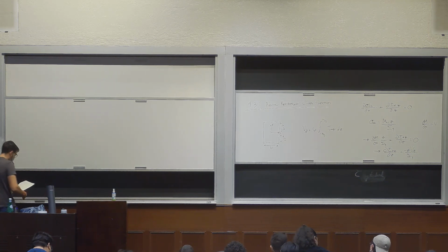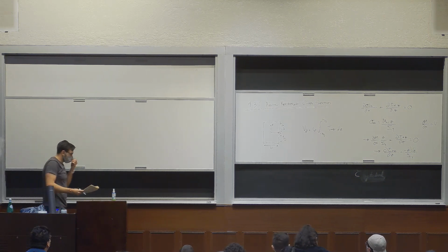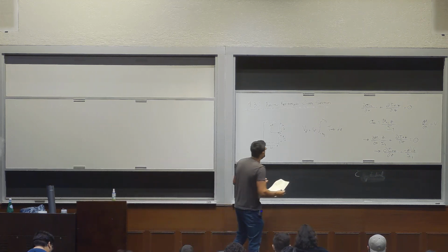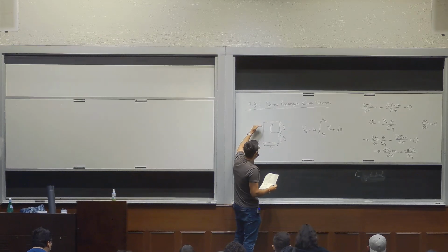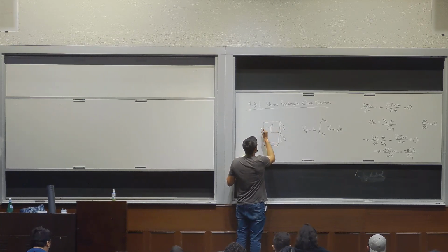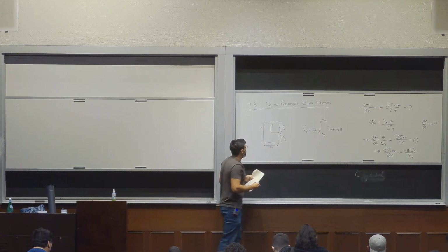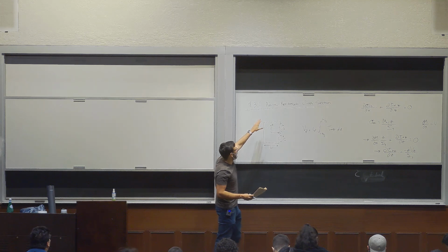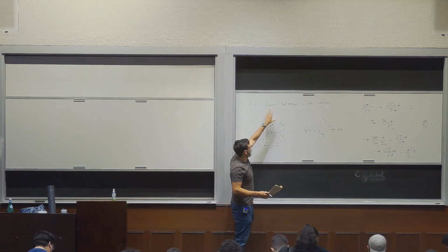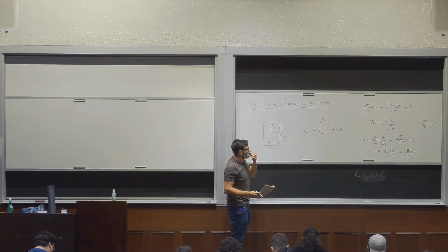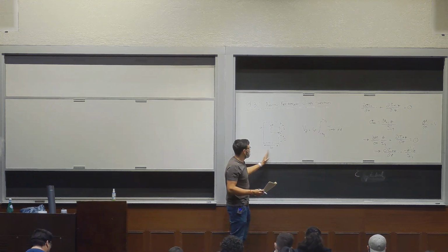All right, so we have that differential equation. What we're going to do is choose an arbitrary z position, let's say this location here. This is z. We want to know what tau is at that point. The reason they talk about narrow in this title, narrow rectangular, is because we're also assuming that this tau xz doesn't vary with the y coordinate.